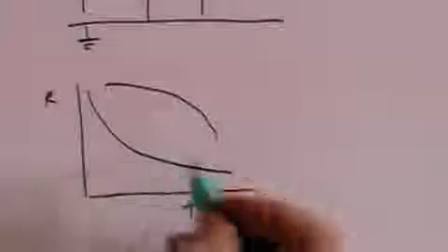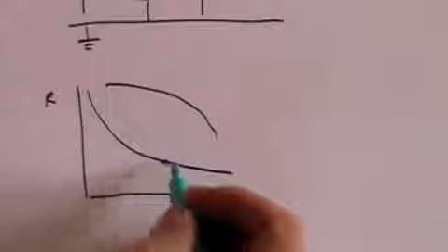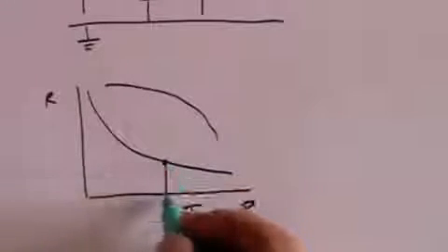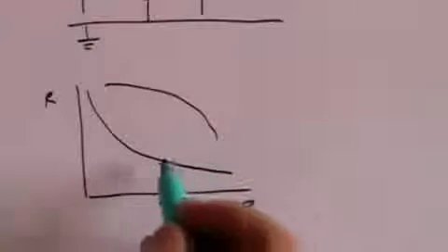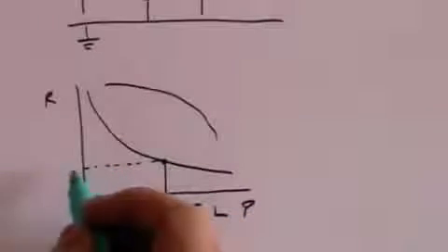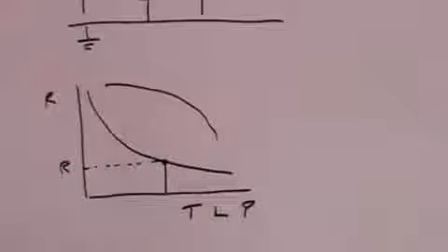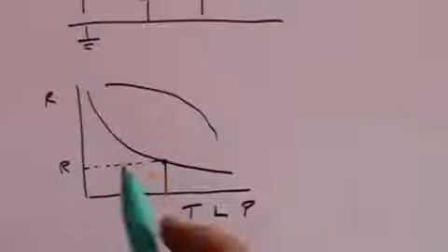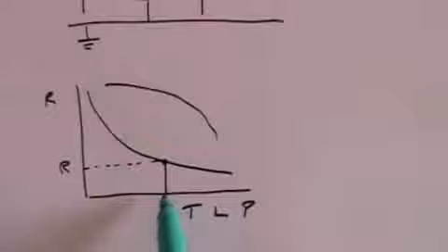And that means that if you want the light to come on, let's say, when the lighting level in the room gets to that value, if this is a measure now of the light, then you want that resistance to be the critical resistance which will cause the operational amplifier's output to change from, say, positive voltage to negative voltage. And the only way you can do that is to calibrate the sensing device first.